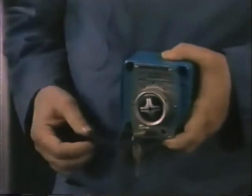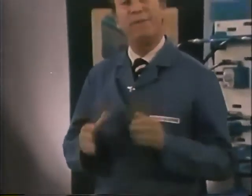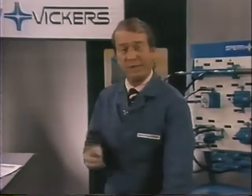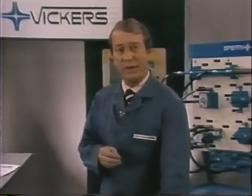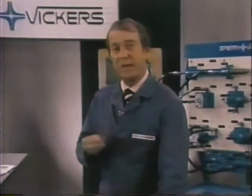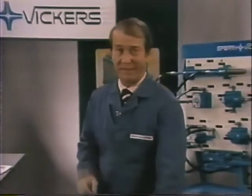Now let's take a look at a flow control that has an additional benefit. We all know that the temperature of oil affects its viscosity. We can get more hot, thin oil through an orifice at a given pressure than we can cold, thick oil. Any change in the temperature of the oil changes its viscosity, which in turn changes the rate of flow through our flow control and the speed of the cylinder.